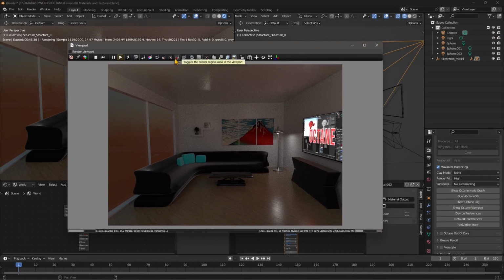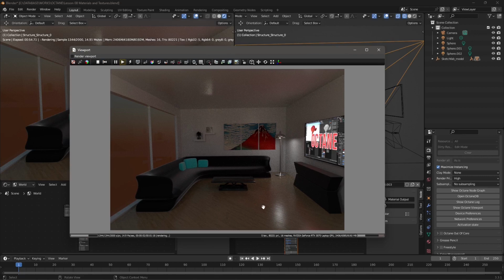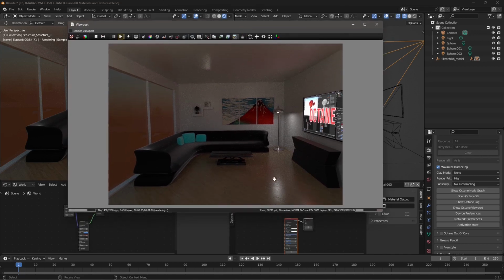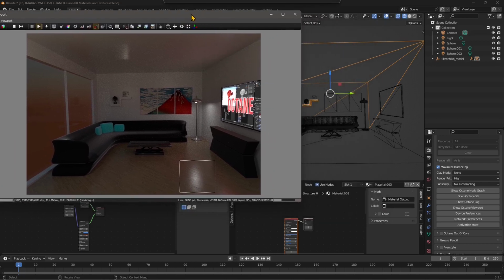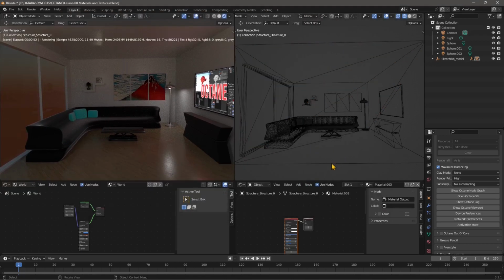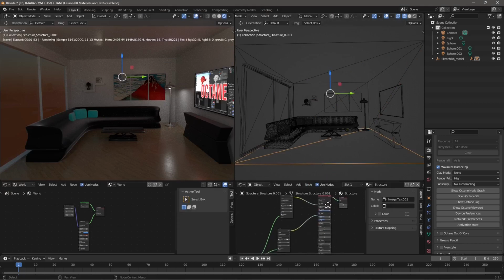But something you also want to try here is to use regions or region rendering. So I've opened up the Octane viewport from the render settings again, and if I don't want to render everything, if I just want to concentrate on one area of my project, in order not to waste too much time in testing the materials, in testing the lights, or part of my scene, I can use the region here. Now you have two types of region. This one here leaves the rest of the image visible. So right now I'm rendering just that little box, but the rendering stays there on the rest of the image.